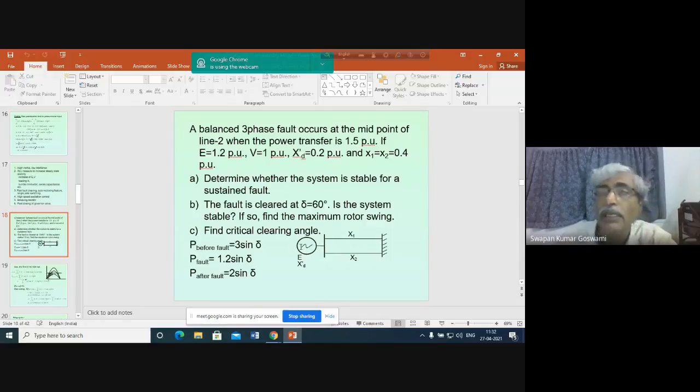Transient reactance. You know that synchronous machines are having three types of reactances. One is the steady state reactance, that is called the synchronous reactance. During normal operating condition, this is the reactance offered by the machine to the flow of current. What is this synchronous reactance? It is leakage reactance plus armature reaction. You know that on the field flux, there is an impact of the armature winding flux.